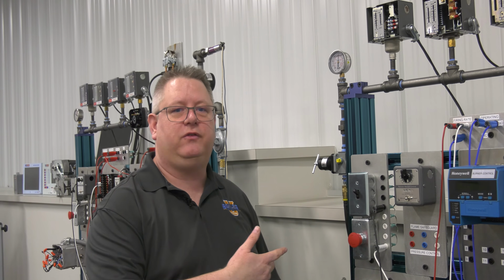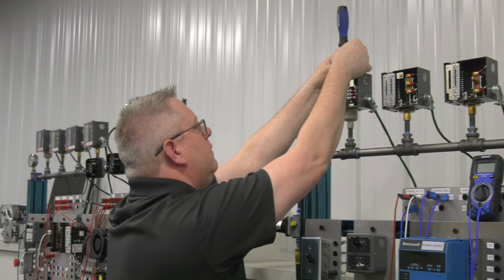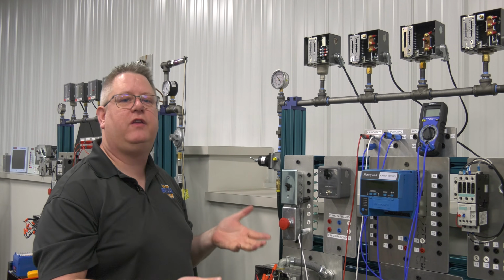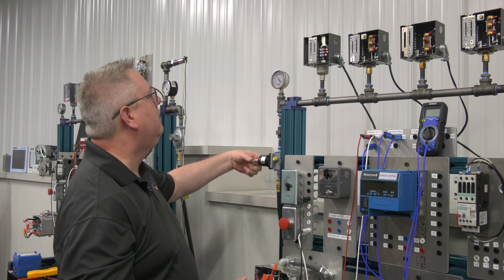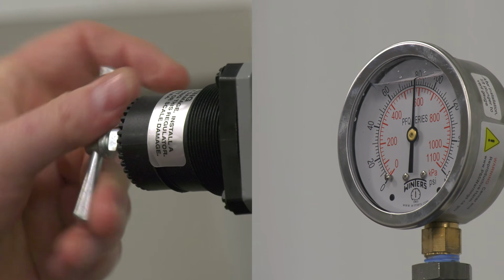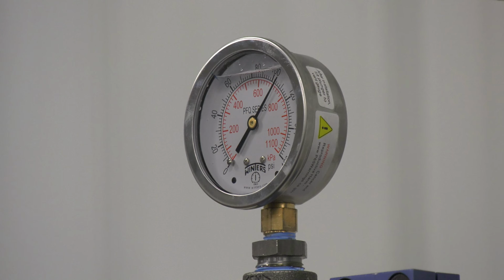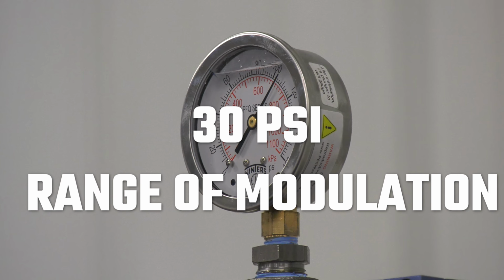So I'm going to make some adjustments maybe to the middle of the range, and we'll look and see what our modulation range is there. Okay, so I've adjusted the differential to the maximum, which is F on this device, and we'll take a look this time and see where that wiper ends its travel, what pressure that's at for those purposes. So at 70-ish, we're starting to modulate, and I can watch that potentiometer throttle really until about 105 PSI. So at the F setting, we're really looking at a 30 PSI range that the boiler's operating at.